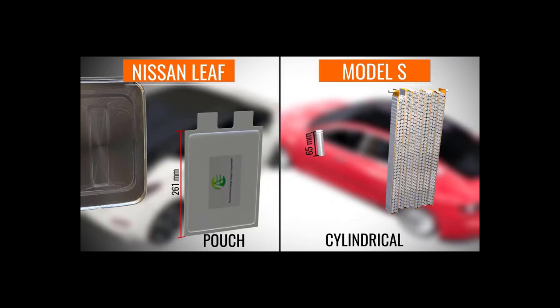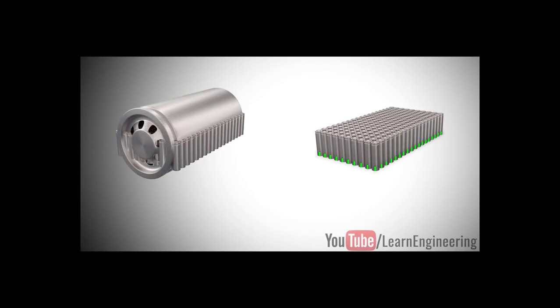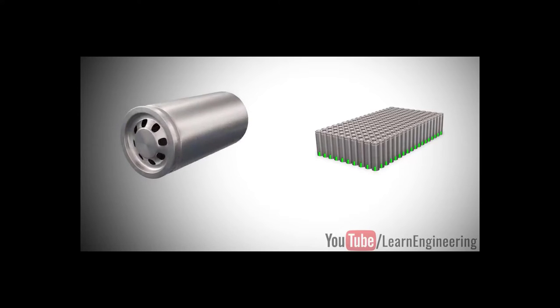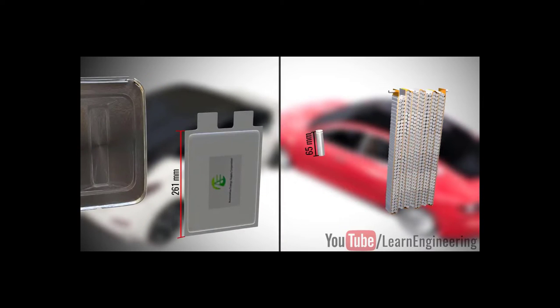The small multiple cell design has one more advantage. During high power demand situations, the discharge strain will be divided equally among each of the cells. Instead of many small cells, if we had used a single giant cell, it would have been put under a lot of strain, and eventually it would suffer a premature death. By using many small cylindrical cells, the manufacturing technology of which is already well established, Tesla clearly made a winning decision.